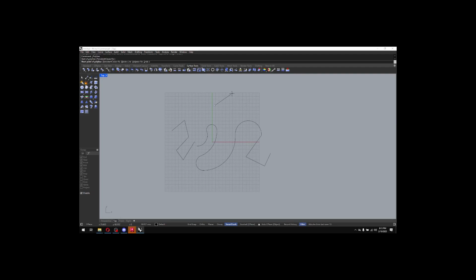We're going to hopefully do 2 more. Once I get to a certain point, I can hit C, enter. That's going to automatically close it. If I'm in an arc mode, it'll close with an arc. Big thing I'm going to push today, next time, every time you hear me talk about software or any of these programs, try to close your lines as much as you can, especially in CAD, because that's going to help you a lot going into Rhino.